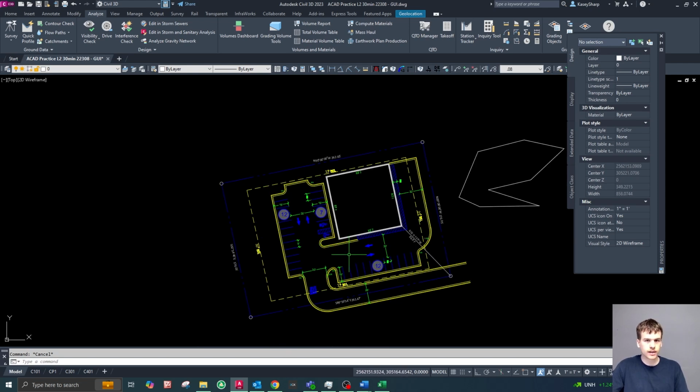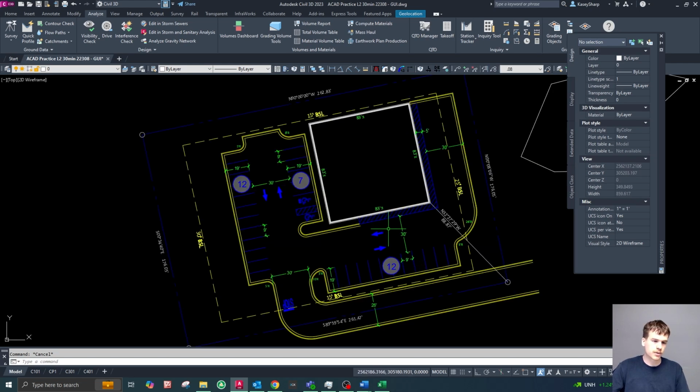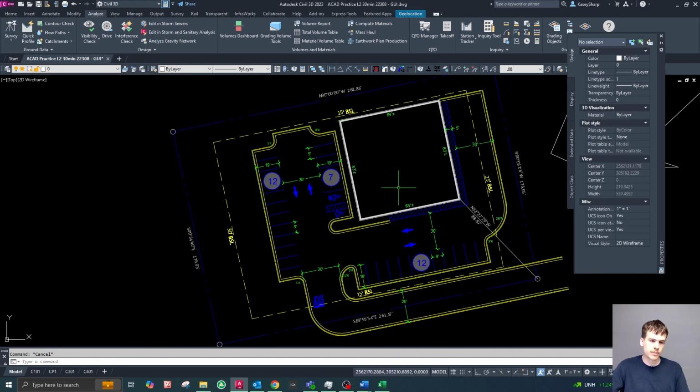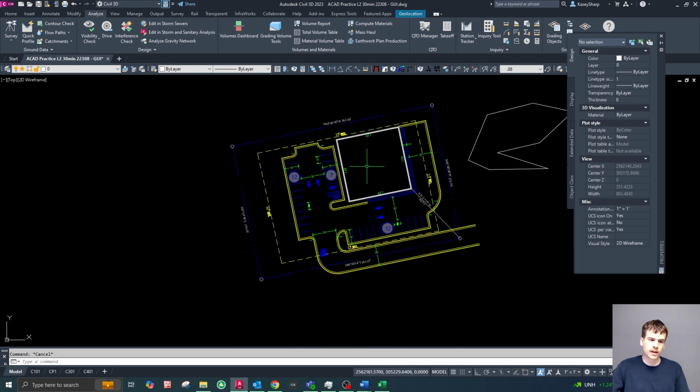You can use polylines, lines, offsets, and arcs to wireframe up your site, and then you can connect it all together using fillets, using more offsets, drawing more arcs, joining your lines and polylines together, and then you could start to apply some of the more advanced commands like CC to make your curb lines show up, etc. So now your site becomes more complete.